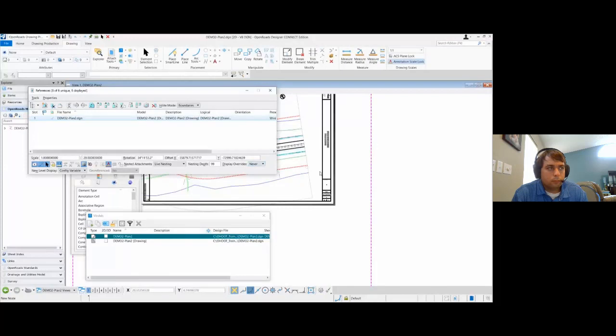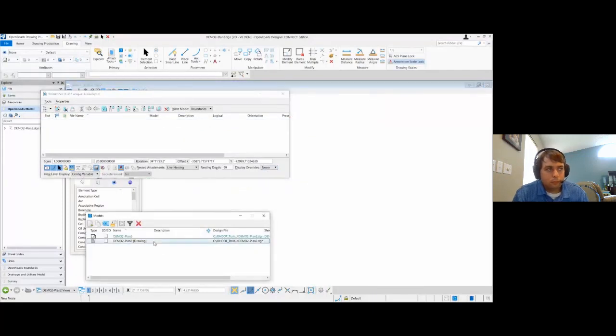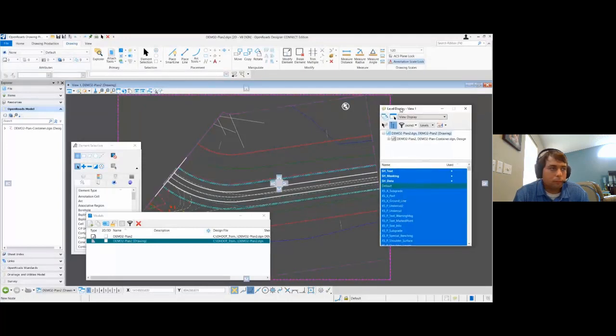If you're cutting sheets using one of our seed files, the name boundaries, that's how they are set up. We did that intentionally so that we can take advantage of what this is really doing. Display overrides never basically means to not allow the overriding of the display. But the thing to remember is that this only affects nested references.